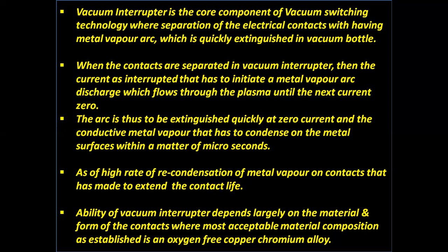The high rate of recondensation of metal vapor on the contacts extends the contact life. The ability of the vacuum interrupter depends largely on the material and form of the contacts, where the most acceptable established material composition is an oxygen-free copper chromium alloy.